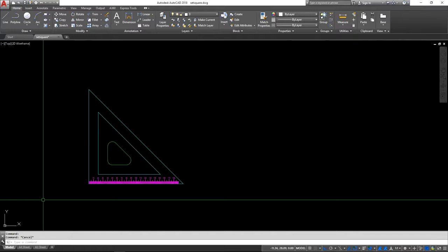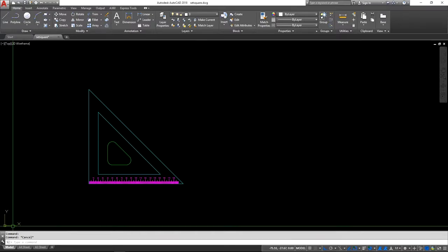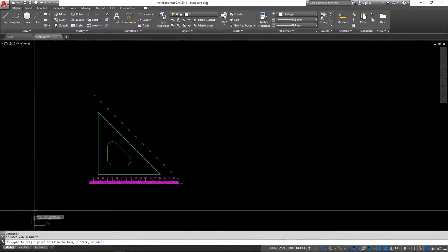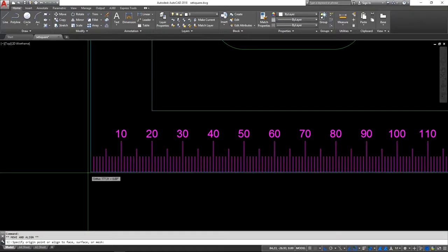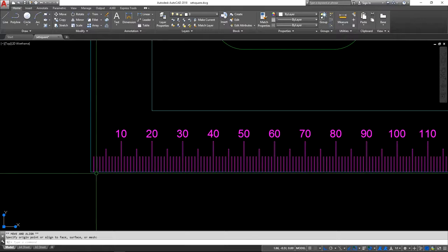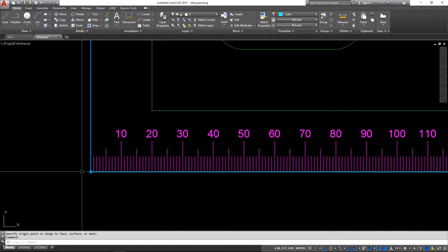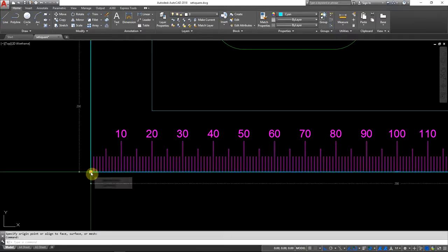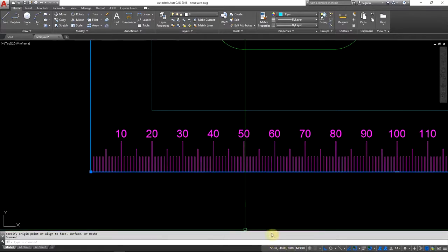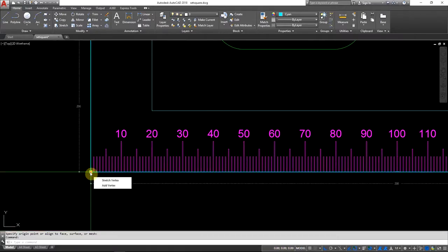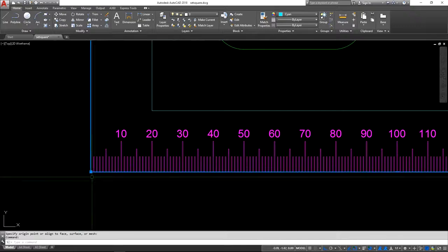Now the easiest way to do that is just to click on your UCS icon, select the center grip, and we're just going to move that. I'm just zooming in onto this corner. I'm just going to click on there, and now what I've done is moved that to 0. So you'll see if I select the outline and I move my mouse over the center point, looking down in your coordinates, you'll see 0, 0, and 0. Just down in here, you'll see all zeros. So that means I've now zeroed that point.